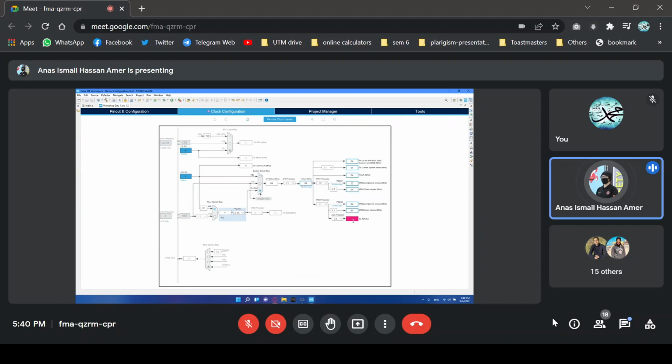The max is 32, but we're now feeding 64. It was not showing an error before because ADC was not enabled. But now that it is enabled, we need to select the ADC prescaler. So let's select divide by 2 or divide by 4. Still not enough, then divide by 8. So this is 8, and it has removed the error. Now we can press Control S to generate the code.